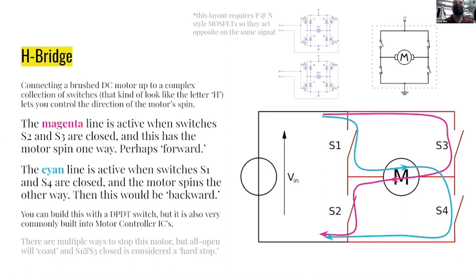This is such a big deal that not only is it useful in the useless box or in other interesting places, this is essentially the control structure that gets built in for just about every DC motor. You want to have an H bridge, and the level of detail or control you can have for that is really what drives it. This is also sort of the first version of what gets used for stepper motors and for brushless motors and all those things. They're all based on this H bridge architecture, where closing the right combo of switches makes things work.